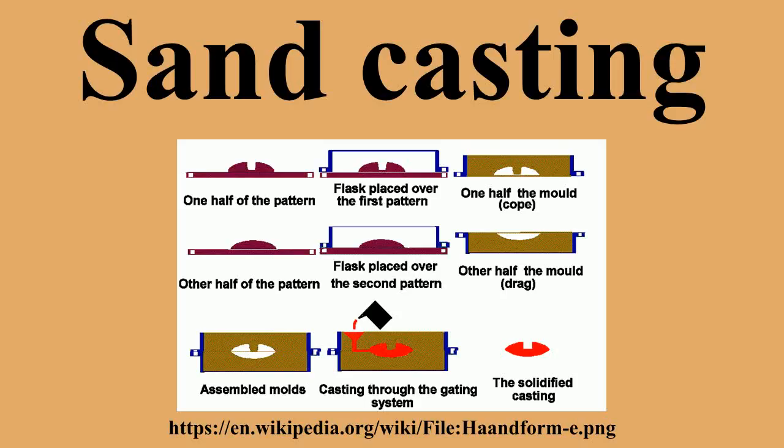With both methods, the sand mixture is packed around a pattern, forming a mold cavity. If necessary, a temporary plug is placed in the sand and touching the pattern in order to later form a channel into which the casting fluid can be poured. Air-set molds are often formed with the help of a casting flask having a top and bottom part, termed the cope and drag. The sand mixture is tamped down as it is added around the pattern, and the final mold assembly is sometimes vibrated to compact the sand and fill any unwanted voids in the mold.